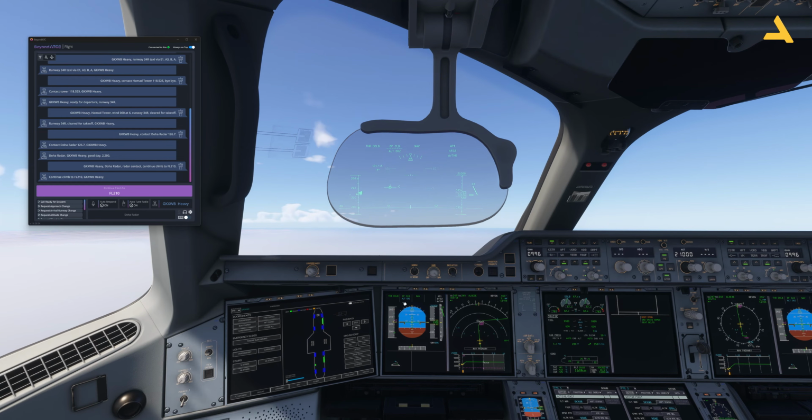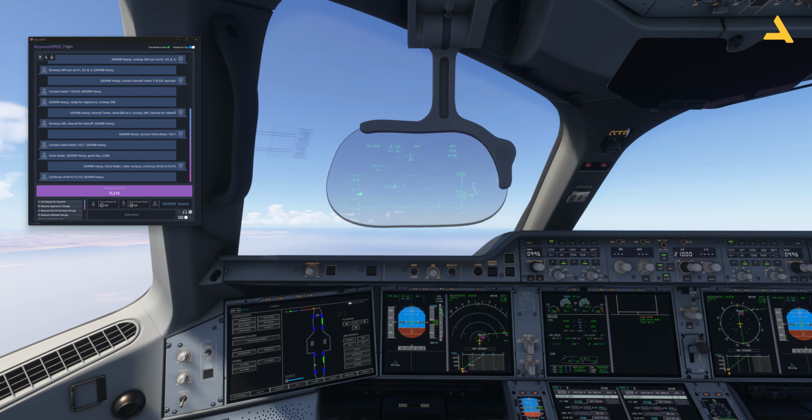That's why right now the climb mode is in open climb instead of the managed mode, because there are some constraints over here. So now I will straight away climb up to 21,000 feet. Similarly for the descent, if you are instructed to descend using a certain STAR, then obviously you will follow all the constraints for the descent. But if you get an altitude, then you just descend to the altitude given to you by the ATC. Right now you can see the plane is climbing up to flight level 210, and it's a short flight.